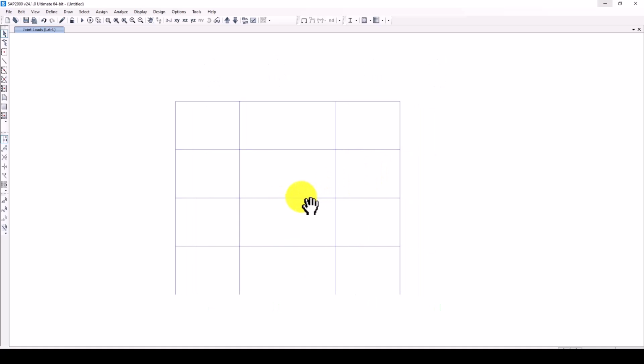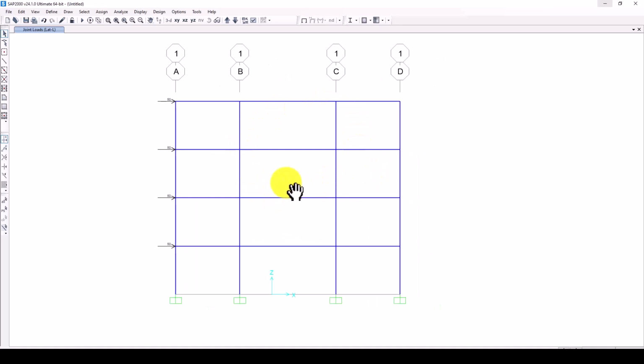Now we have finished. This is an existing building, applying all the loads, including the equivalent lateral load from the self load of the structure. Now what's next? We must define some sort of nonlinear behavior. So we have a distributed model which is not applicable here. We use what we call the concentrated method, or hinge, or rotational hinge technique.